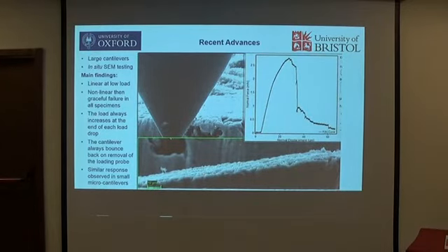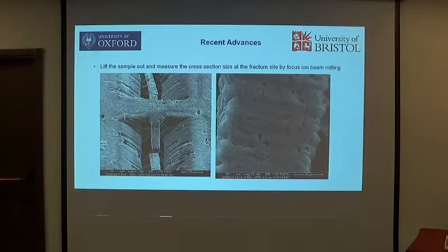Interestingly, after removing the load, the cantilever always bounces back, although there's a large fracture, more than half of the section already. I observed this as well in the smaller cantilevers, about 10 micrometers. Still trying to understand why. Probably because there's some sliding that pulled the graphite cantilever back. Again, that's the in situ testing.